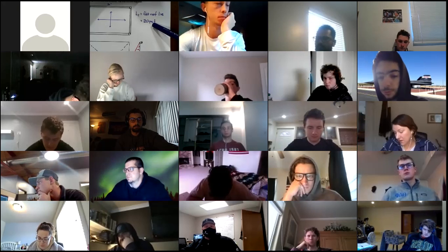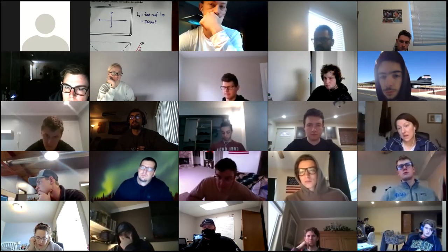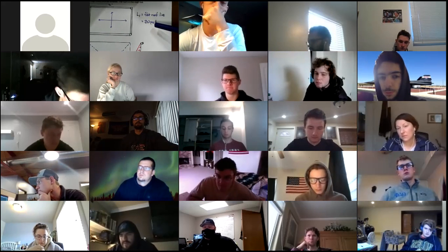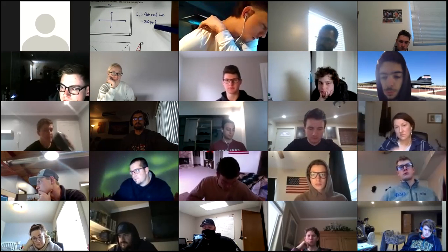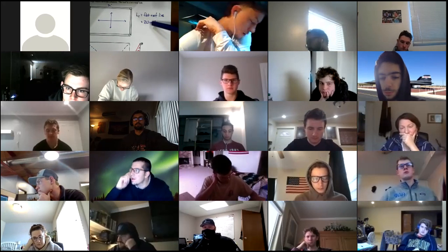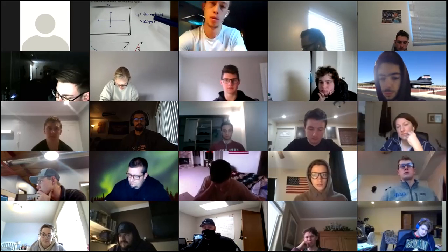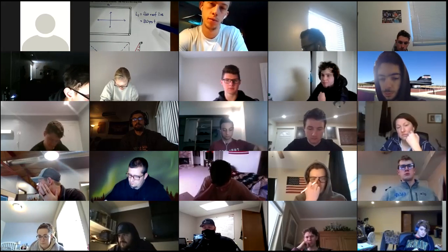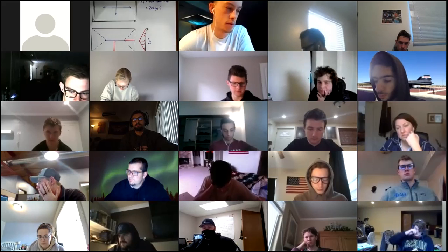All right, so back to this, 20 pounds per square foot, that's pretty light because you don't generally have parties on roofs. Well, actually you do, right? If you have access to it, people like to go out and have parties on roofs. Or you go to a restaurant and they have a rooftop bar. Well, you have to design it for a higher level of load than 20 PSF. In that case, that would be a special use that you'd have to deal with. The live load we're talking about here is temporary placement of roofing materials, temporary placement of equipment or people up there, because we often have rooftop mechanical units that we have to service. That's the kind of live load we're dealing with here, and why it's so much smaller.